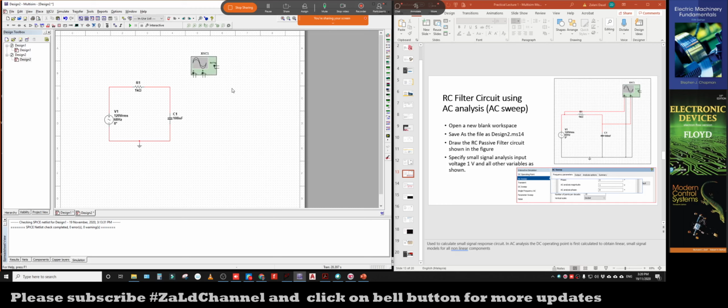Now, the oscilloscope is different from the multimeter. For example, this oscilloscope has 2 channels, the A probe and the B probe. Each of A and B has plus and minus terminals. So let's say in this RC circuit, I am going to measure the input voltage, the input signal. I connect the positive terminal of A to here, and then the negative terminal of A to ground.